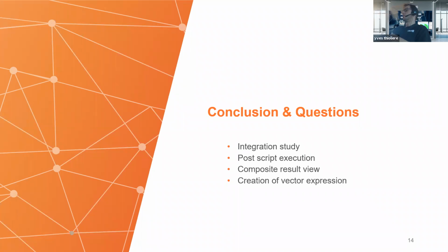But if you are using the accuracy priority type, this map is a kind of parametric calculation. So it's in fact the real FEA calculation of the working points. So it's the same accuracy as a JMAG calculation, including all the 3D effects if you are using a 3D model, including all the AC losses if you're also using FEA conductor. So that's very accurate.